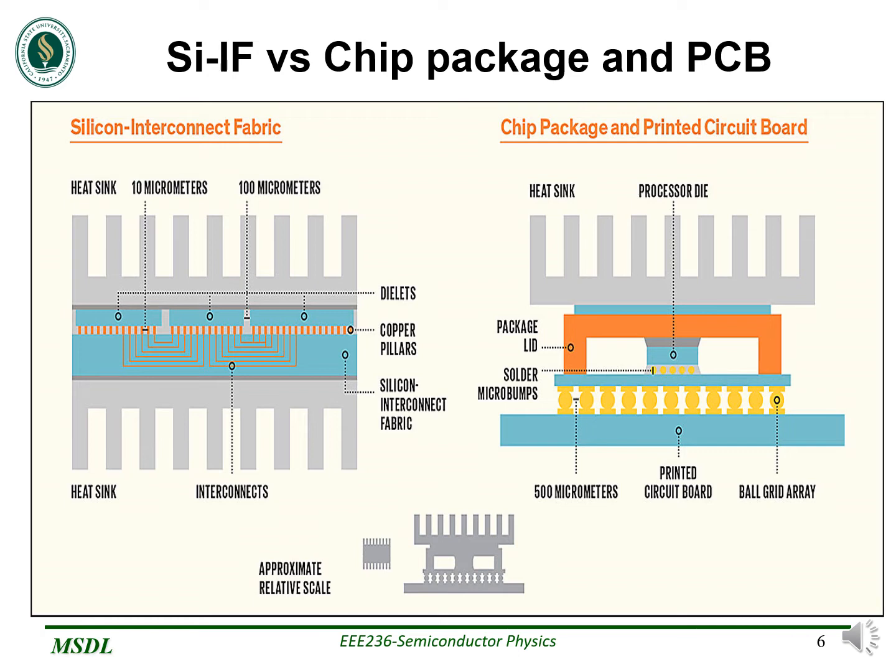The limitation of the solder bumps combined with surface warpage means these solder bumps can be no less than 0.5 mm apart. In other words, you can pack no more than 400 connections per square centimeter of chip area.